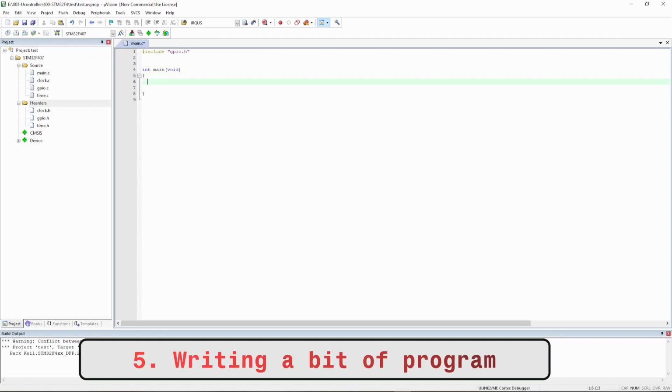This function will help us to change the status, first of all to select which status for the pin. We will see later on all the statuses of the pin that can be selected, but as we would like to toggle the pins, we need to select the pin as an output mode, so it can be turned on or off, and then control the status of the LED.